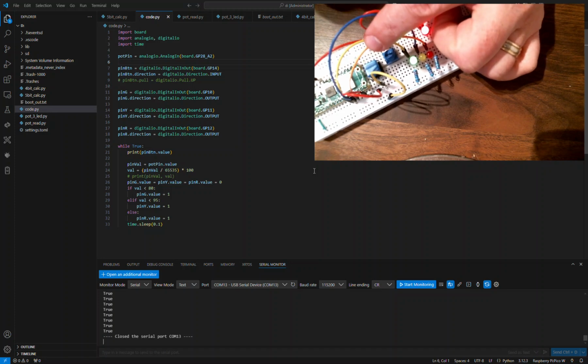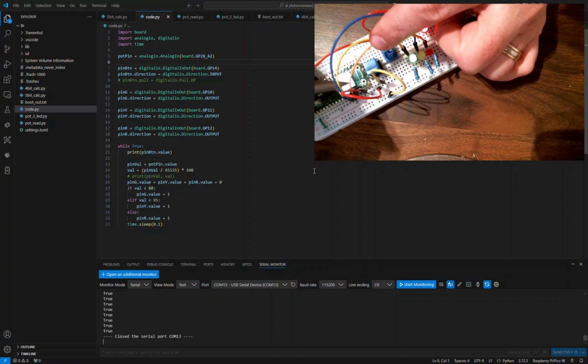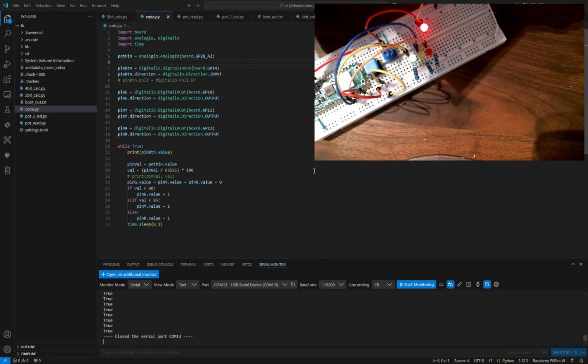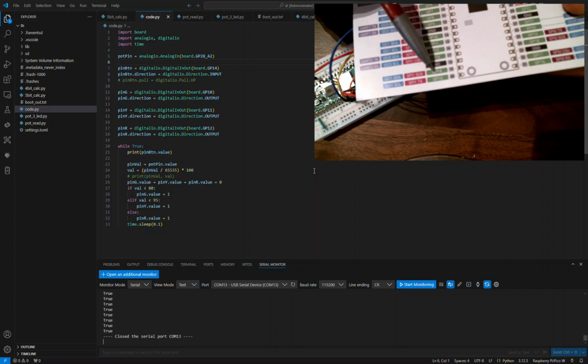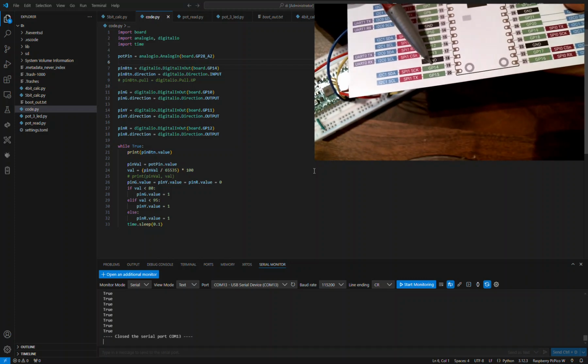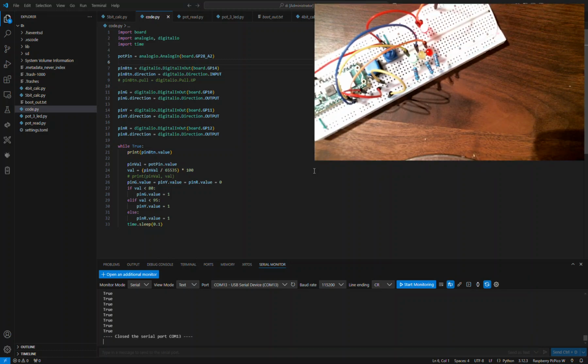So that's why with this button here, we have some additional wires here. One is going into one of the leads, and it's coming out of the second pin on the left-hand side, which is going to be GPIO 14. So that's the lead we're going to use. And we're going to reference it with GP14 because it's going to be just a digital pin input output, and we're going to use it as an input here. So then we have the other lead going to ground.